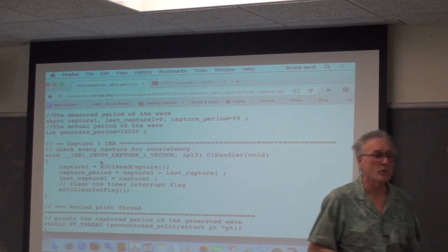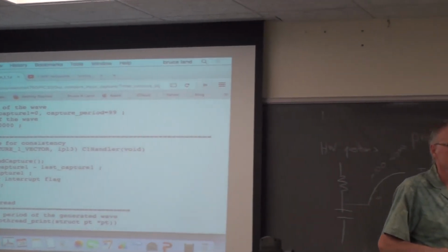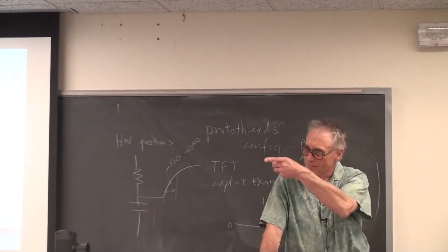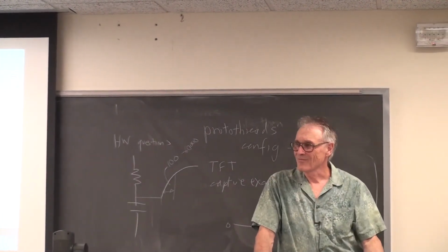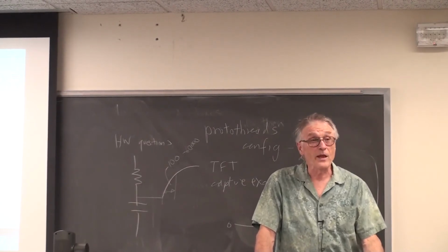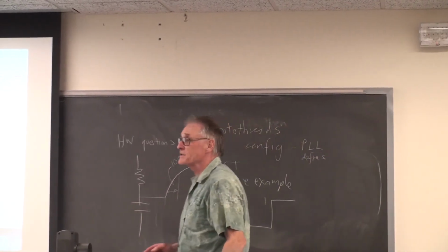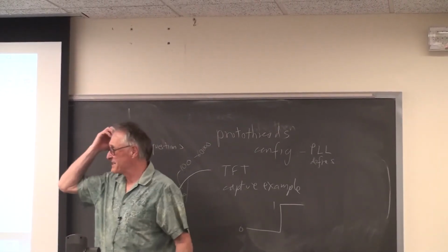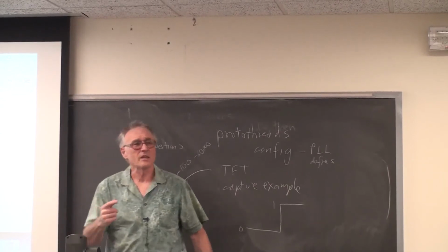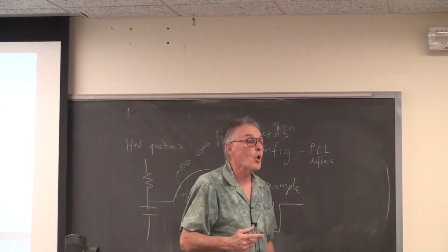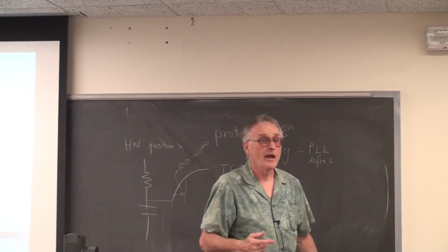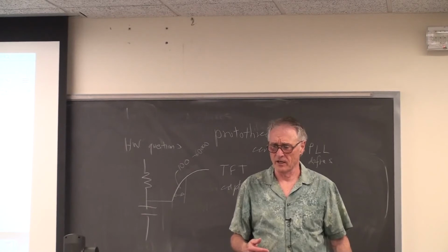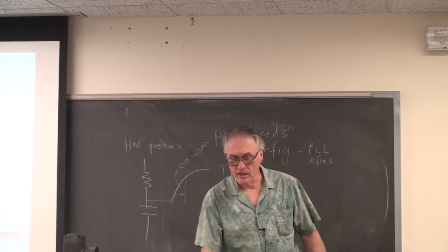And what happens if you don't clear that flag? What would you guess happens? I guess it would never fire again. That's one reasonable guess. In fact, it fires all the time. Those are the two possibilities, right? And in this case, it fires on the next available machine cycle forever. And you say, huh, that's funny, my TFT went dead. Must be a bad TFT. So always clear the flag.